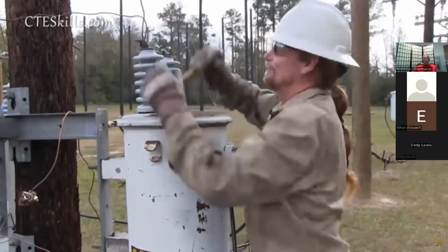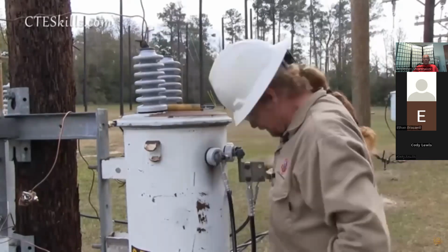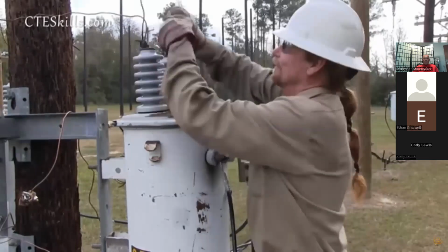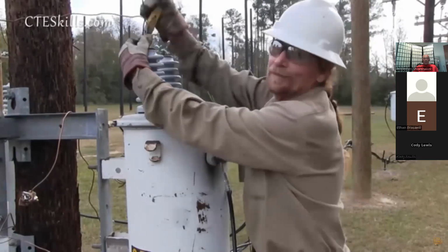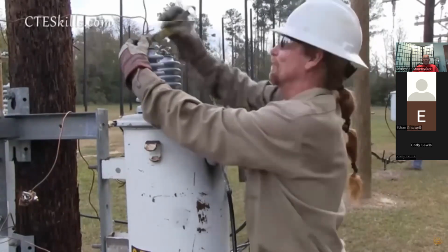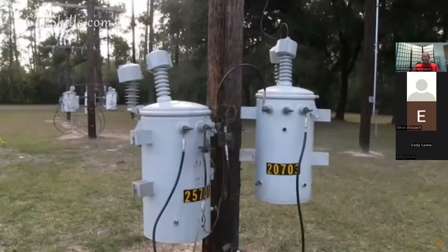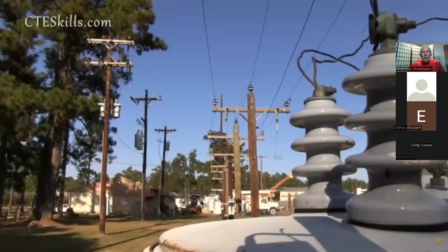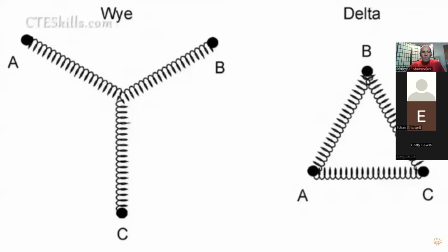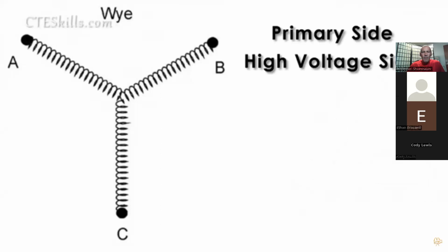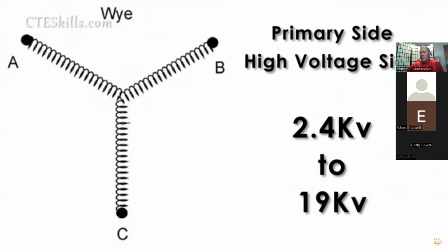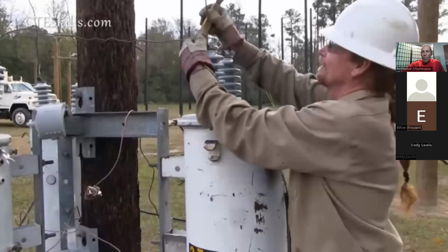That's by itself. That's for smaller amounts of power. Now there's several different types of three-phase banks and different voltages, so knowing how to wire these up properly and how to handle them is really important. It's something we go through here in training. On this particular section, we have 5 different banks set up, and we can wire these in different configurations. Like this one, this is what we'd call a Y delta bank.